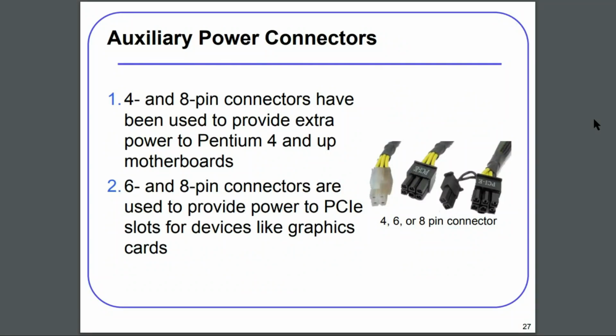Now these are the auxiliary power connectors: 4, 6 or 8 pin connectors. 4 and 8 pin connectors have been used to provide extra power to Pentium 4 and up motherboards. 6 and 8 pin connectors are used to provide power to PCIe card slots for devices like graphics cards. So let's move to the next slide.